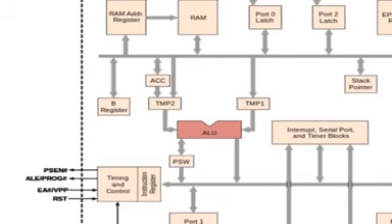There are two more important things. Whenever you do a multiplication and multiply two 8-bit numbers, sometimes you will get a 16-bit result if the numbers are big. Generally in arithmetic operations the result is stored in the accumulator because it is the destination register, but a 16-bit result can't fit, as it can store only 8 bits.